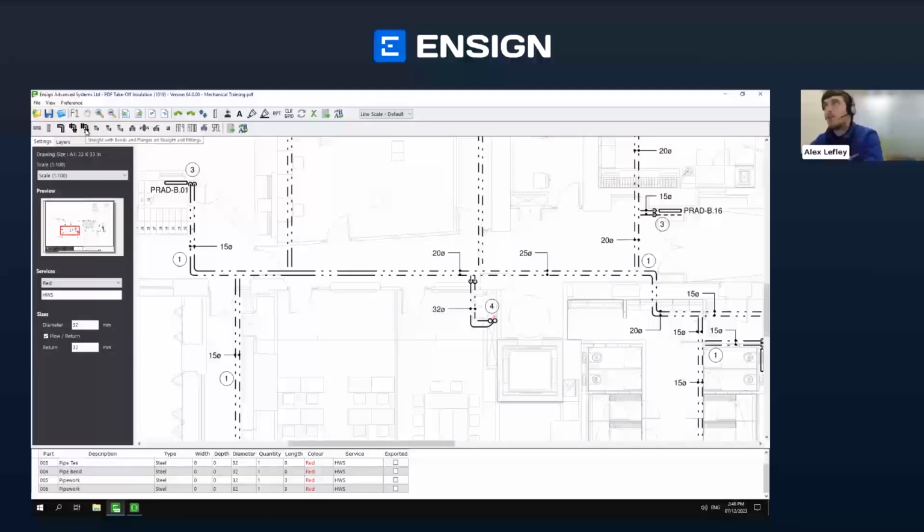And then you also have this option here as well, which is going to do straight with bends and allow the flange on the straight. And for every time you do a change in direction, it will also allow the flanges for you on the bends as well. So you pick which one's relevant to you. So what I'm going to go for is the straight with bends, the nice, easy one. So I'm just going to select that.